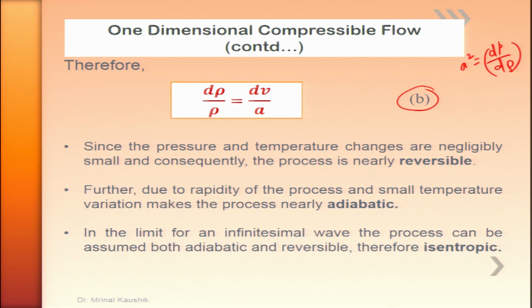Speed of sound squared is nothing but the derivative of pressure with respect to density, but we still have to make some arguments. We ensured that the hypothetical piston is moving at a very small speed, so that the flow is reversible. Furthermore, since we are not allowing sudden changes in the flow situation, temperature effects are ignored.